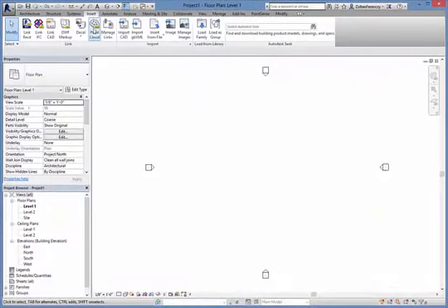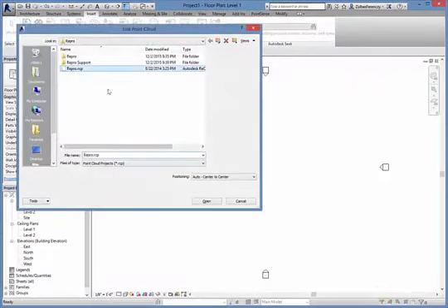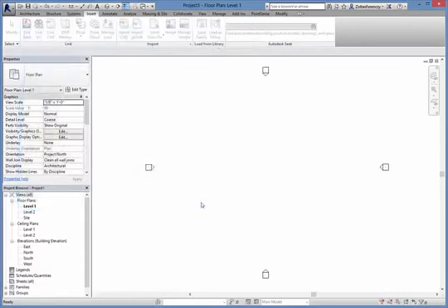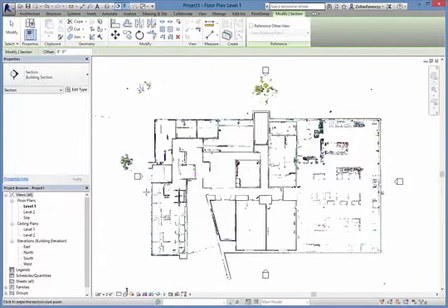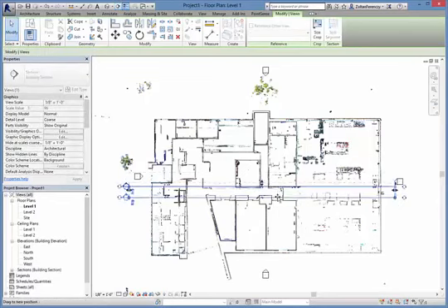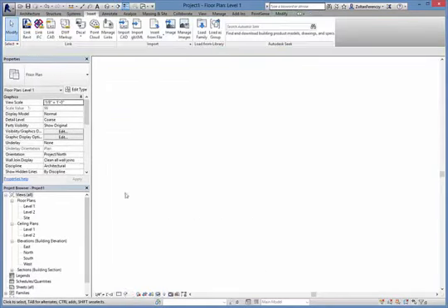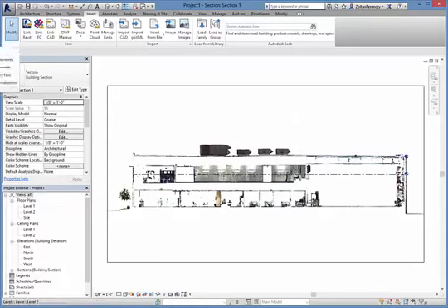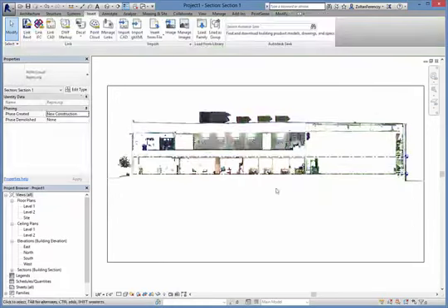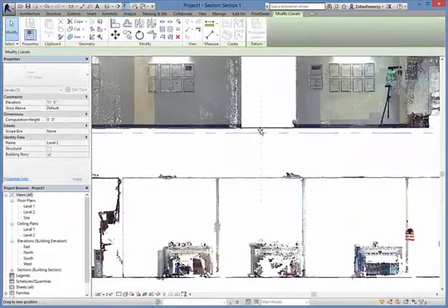Now we are in Autodesk Revit, where we can attach the point cloud to a project as a link. We're going to start by creating a section view to align the point cloud data with the level datum lines that we established for the first floor and second floor of the building. This will allow us to create accurate floor plans for modeling the building to create a complete building information model.